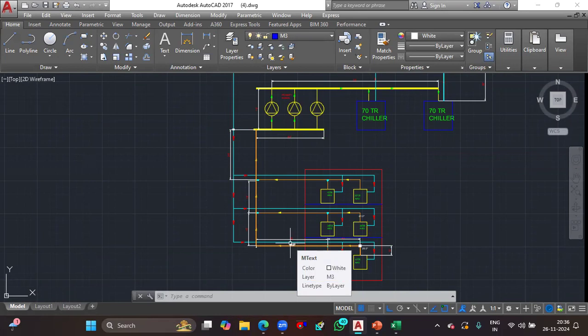So initially we find out the actual head loss with the help of some constraints, with the help of the pipe size or the graph method, whatever, you'll be getting those values. Initially we started with finding out the head loss of straight pipes. Down the line, we bumped into fitting loss, especially those elbows, reducers, T-junctions, isn't it?